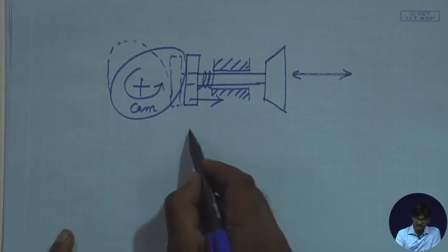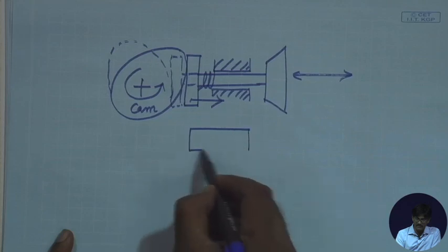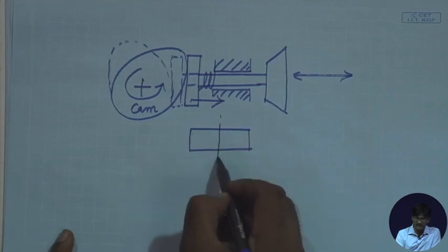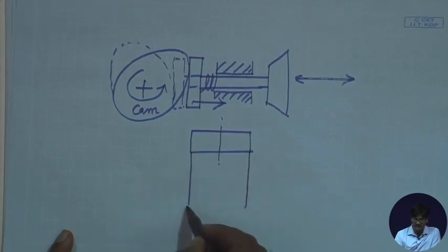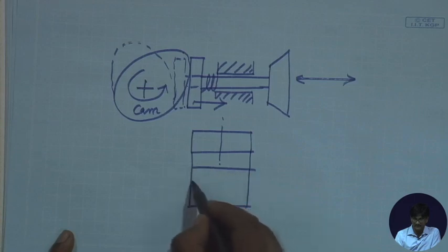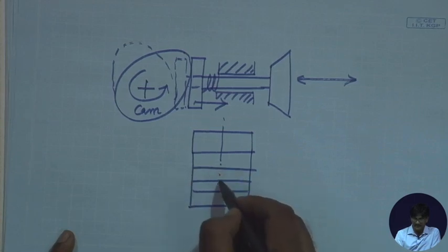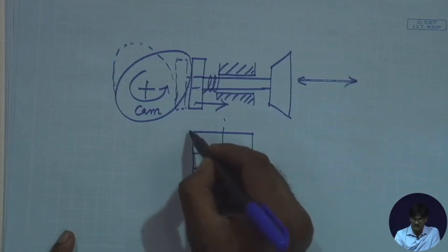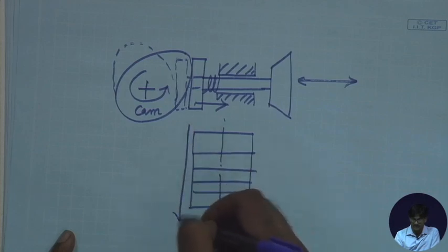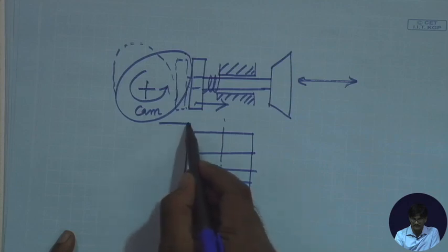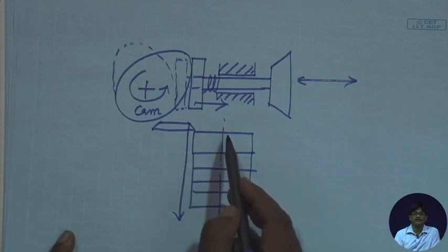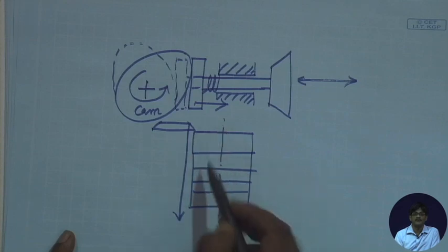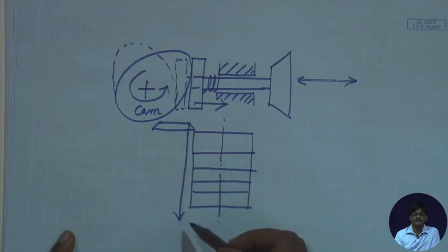That is because the width of gear which is being cut might differ from case to case, or you might be cutting a stack of gears like this. A number of gears in a stack can be cut by a single stroke of the cutter. Up, down, and gear number 1, 2, 3, 4 together can be cut. So, this stroke length very frequently has to be changed.